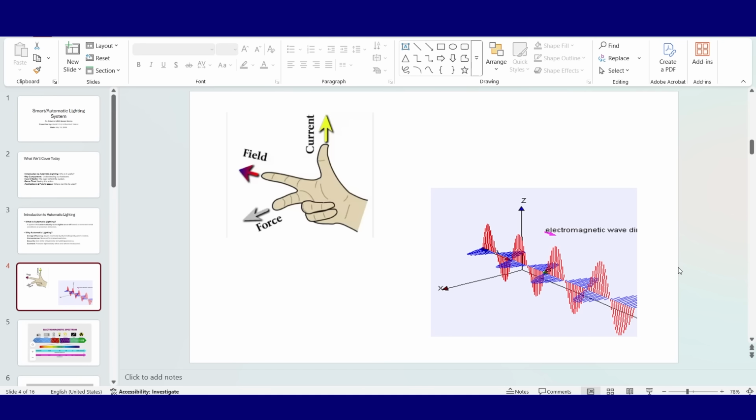The IR infrared is a part of the electromagnetic spectrum and it transmits from one device to another device. It carries data from one device to another in the electromagnetic wave format. It has its own frequency of 38 kHz and a wavelength ranging from 750 nanometers up till 950 nanometers. So that is why we have to discuss some time